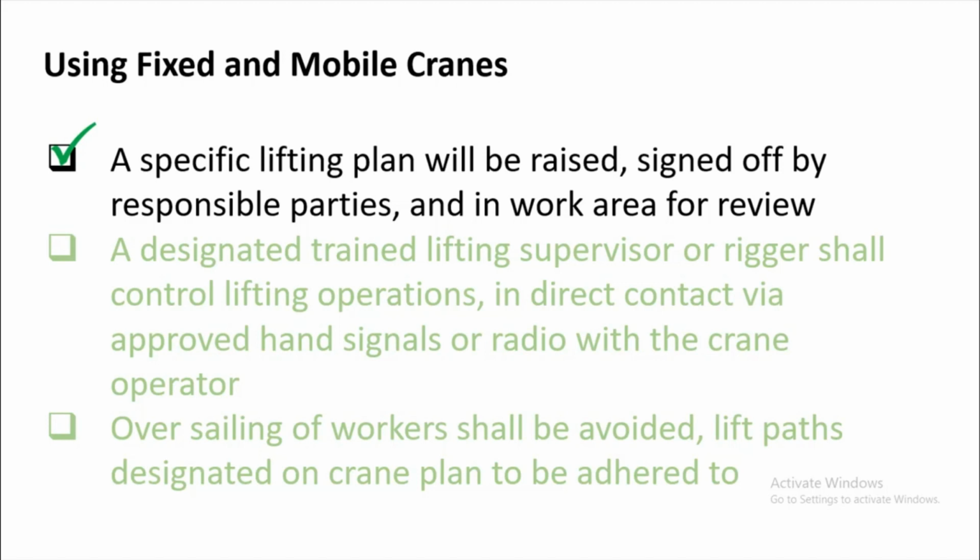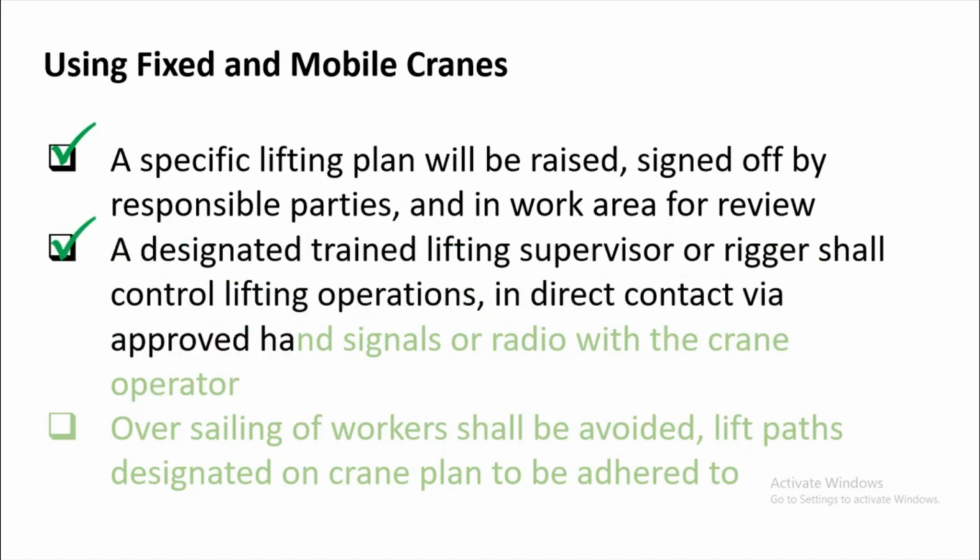A designated trained lifting supervisor or rigger shall control lifting operations in direct contact via approved hand signals or radio with the crane operators.